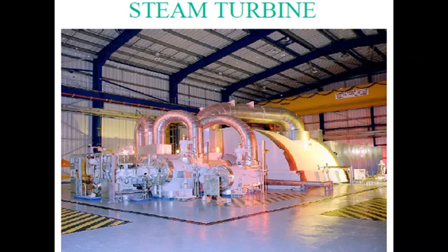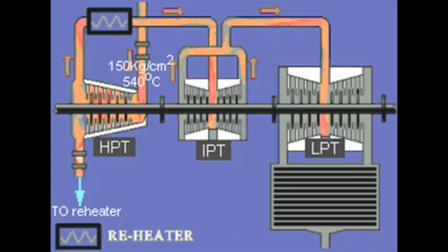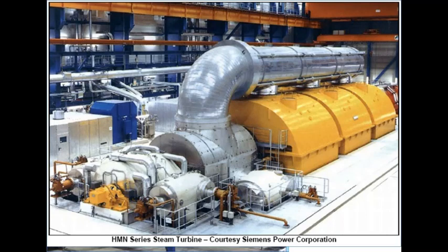So in the HP turbine, we have high pressure expansion, and we have an arrangement to control the steam injection within the turbine by governing, and we have nozzles. Besides that, there is bleeding from the HP turbine. These bleed steams are used for the regenerative feed water heating system, particularly high pressure heaters, where a non-contact type heating arrangement is there.